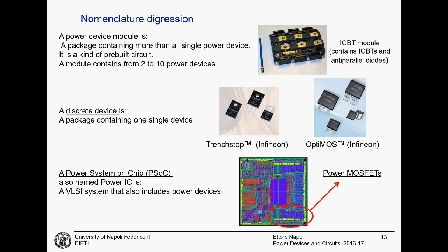And actually it will carry more or less 1 million times more current. If you have, I don't know, 10 to the minus 4 amps in a single MOSFET, this will go easily to 5, 10, 20 amps, depending on the size and resistance. And these are very important for example in automotive applications, when you want to reduce the cost as much as you can, and hence you want to integrate the controller and the power devices in the same chip.